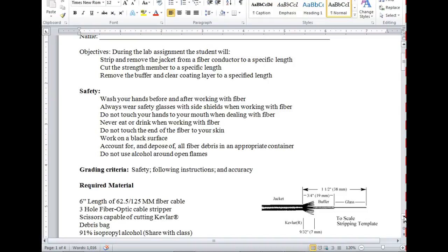And when we pull this stuff, what are we going to pull it by? What would you think? We have to pull cables through conduit, right? Or fiber, we usually don't call it conduit. They call it ductwork or ducts. Okay. Which one of these things are we going to pull it by? Just right off the bat. Pull it by the Kevlar.